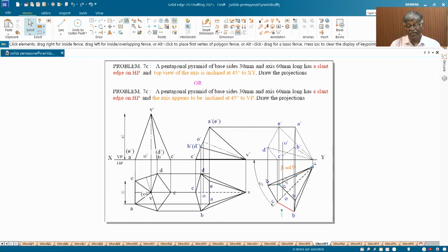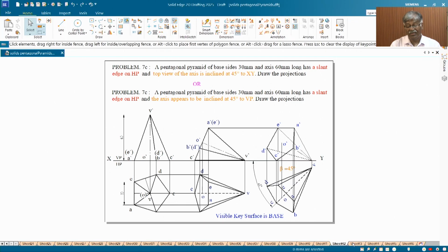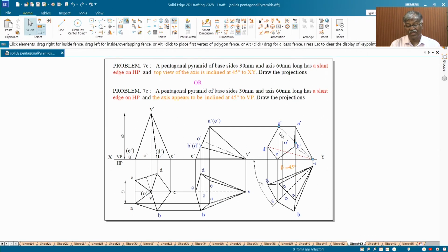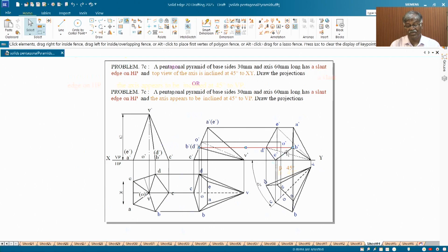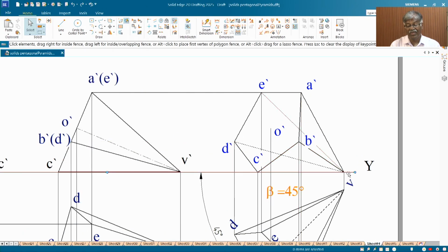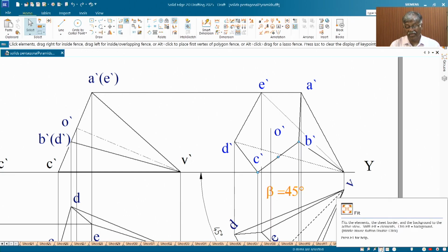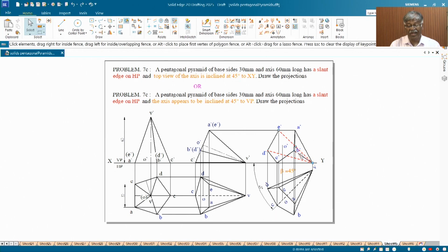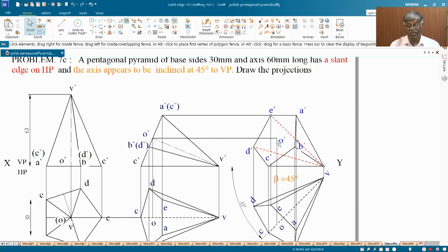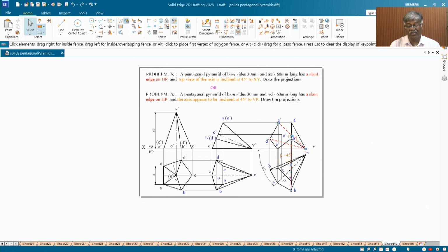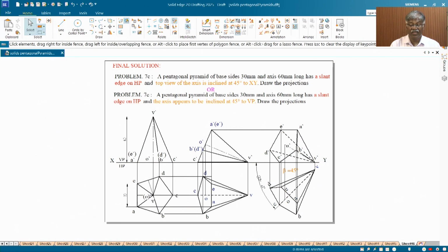Again here you can take the key surface method. Then boundary lines dark, visible key surface dark, boundary lines dark. Then the visible bends. See, BV is visible because CB and AV are visible. Then the crossing line, red color I have used for crossing lines. Okay, visible surface, invisible line. Okay. Now finally you mark the axis also. That completes this problem.